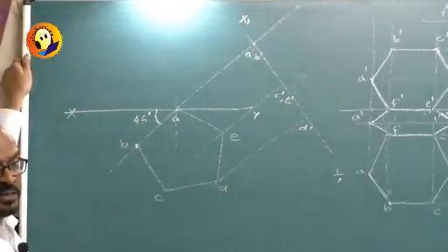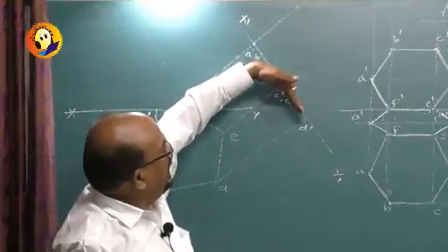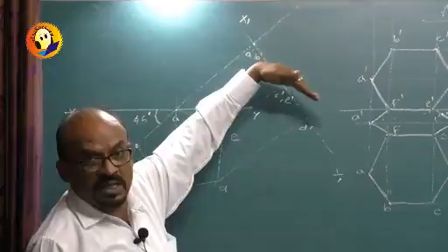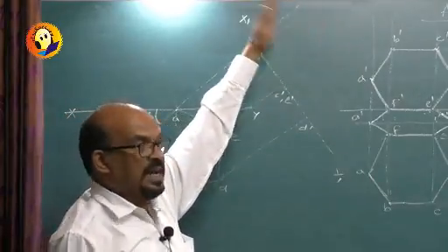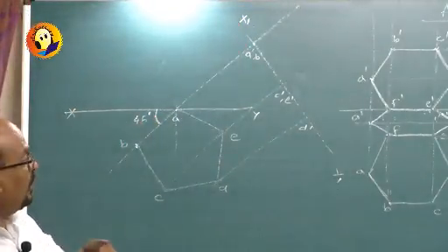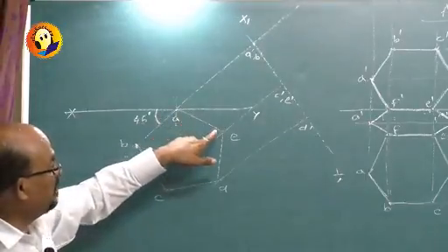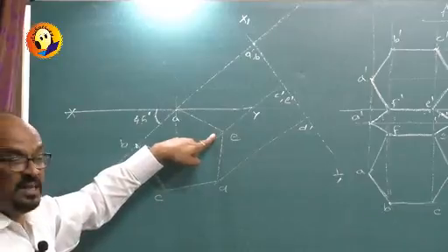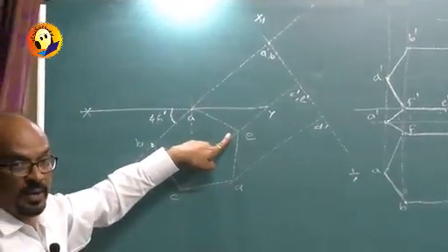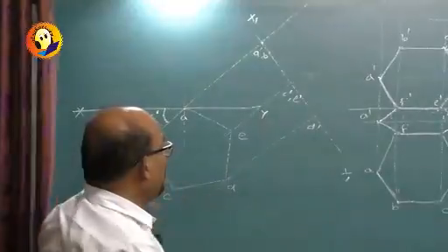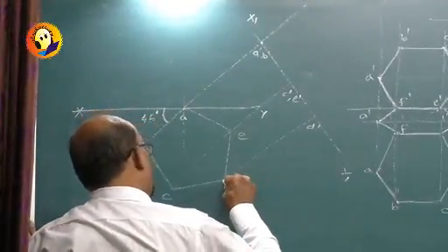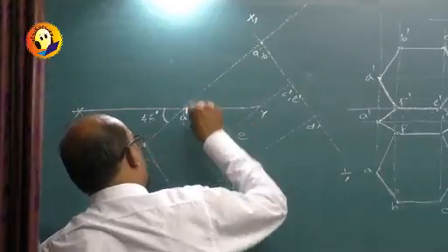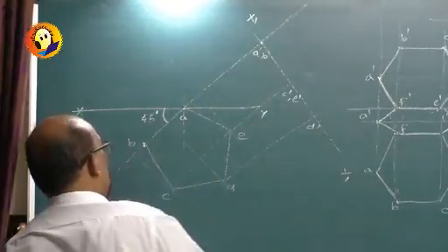Now what he wants us is, about A dash, B dash we should be rotating it. Now how far can we rotate? Because there is a limit. When we rotate, it is likely to cross even VP also. But what he is saying is the adjacent side, that means AE, should be in VP. If the line is in VP, its plan must be on XY. Now I start rotating. What will happen? All the points will start moving parallel to the new XY.